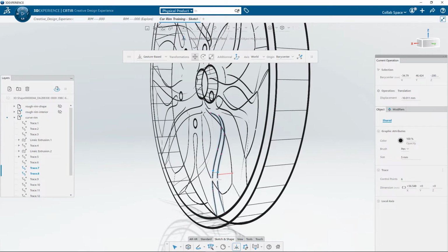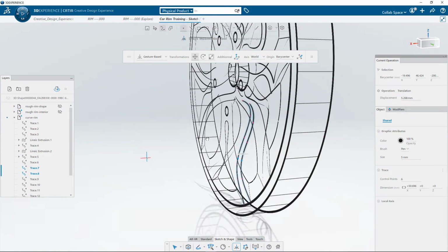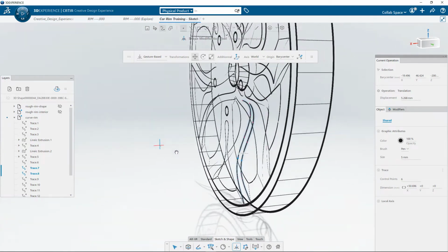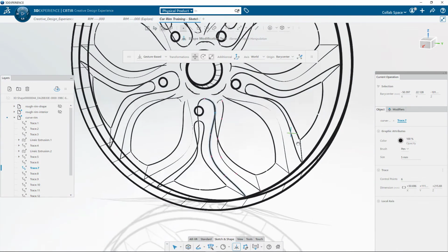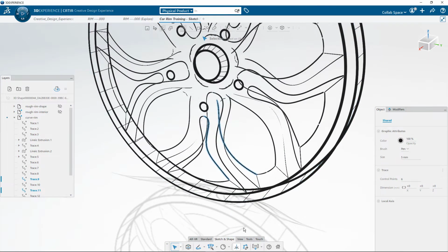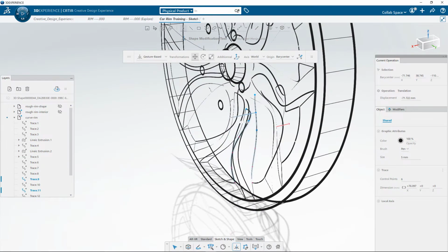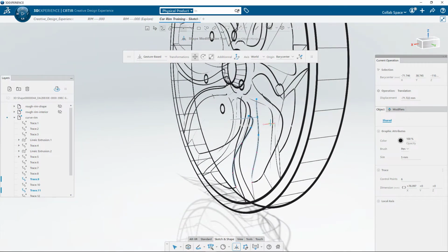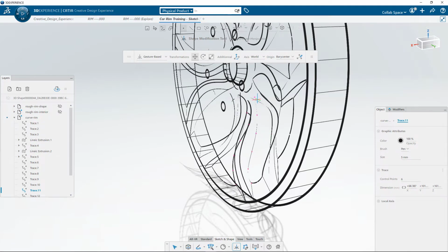For multi-selection, I am now working in explicit selection. You can see the vertices selected and it's possible to move them from the distance. I now change the isolated curves with selection command and move the new ones in reference to the previous one. If I want to go back to implicit selection, I simply need to click one time in space to empty the selection. Like that, you are now able to very quickly manipulate the control points with implicit selection.